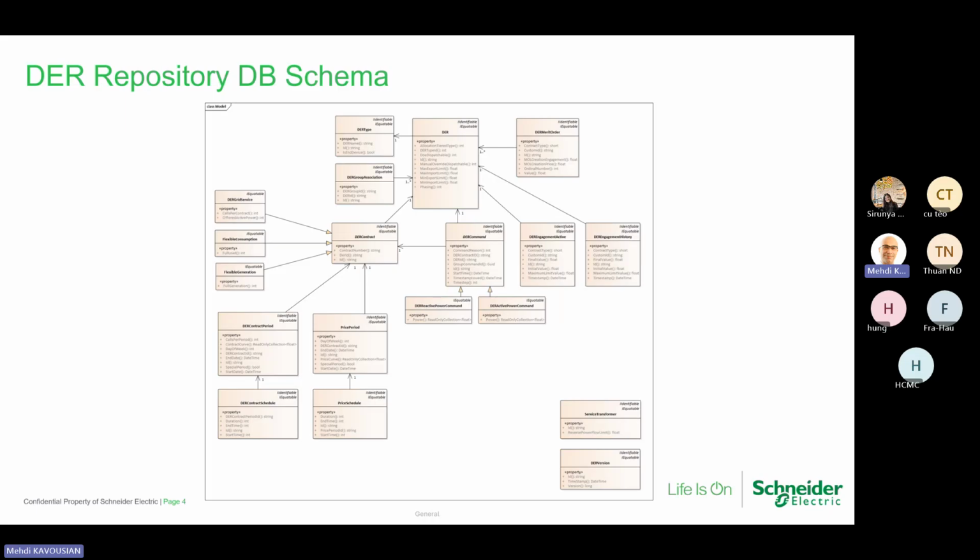When you send the command, it goes to this engagement list. It's a list of things. Next time you run active network management, because it runs periodically, it first looks at which assets you have engaged before, and disengages them, because now maybe the constraint has gone away. Maybe the load is now lower, so I can disengage them. So first it disengages the previously engaged elements.